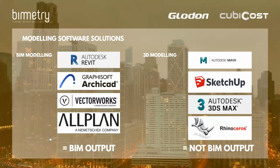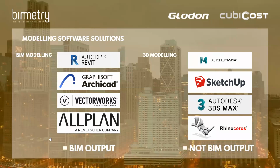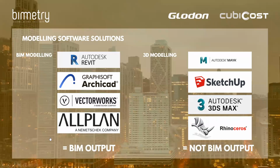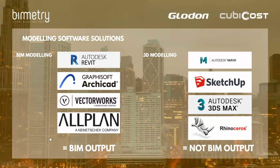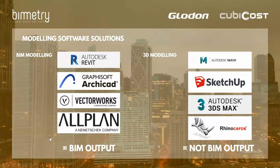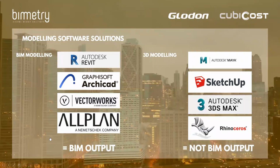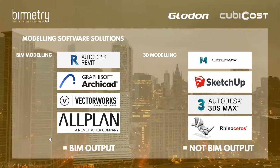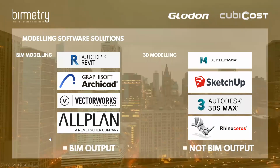The 3D modeling software, such as SketchUp and Rhino, also generate 3D geometry, but it doesn't have the metadata that the BIM models usually have. There are plugins and workarounds to turn this 3D geometry into BIM models, but essentially this is the major difference. Revit produces 3D geometry and metadata information, while 3D Studio Max is used when we only need 3D representation without the additional information. This is good to remember, as if you hear that a certain model was created in Rhino, then you might not have the data you need from this model.